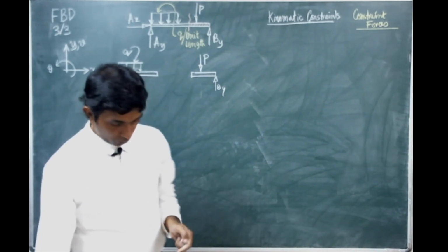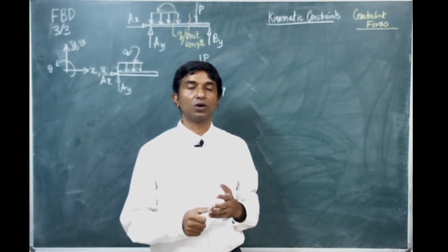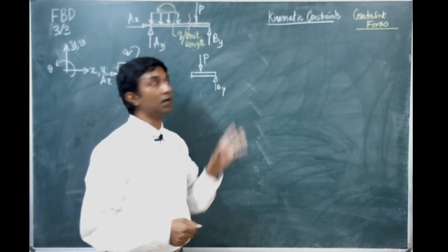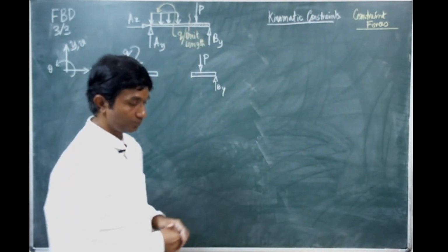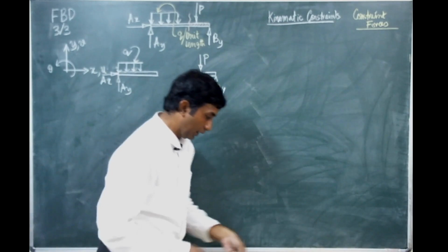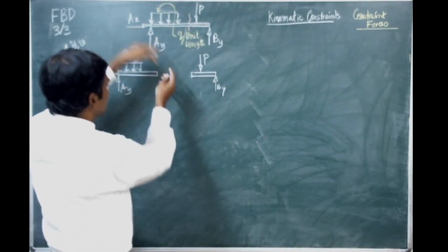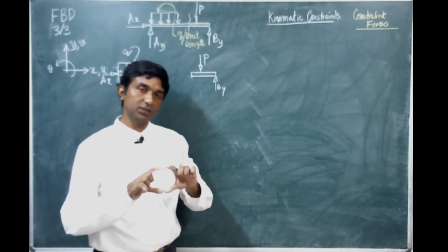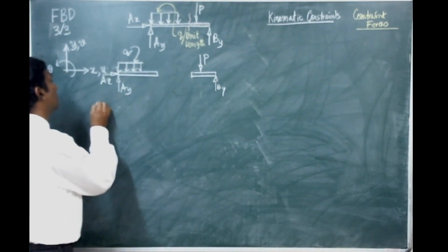So, what would be the consistent constraining forces? In order to understand that, you need to identify what are the kinematic constraints we have at this section. Okay, so in order to illustrate that, we need to consider a big picture, and here we assume that this beam is prismatic and having a rectangular section.